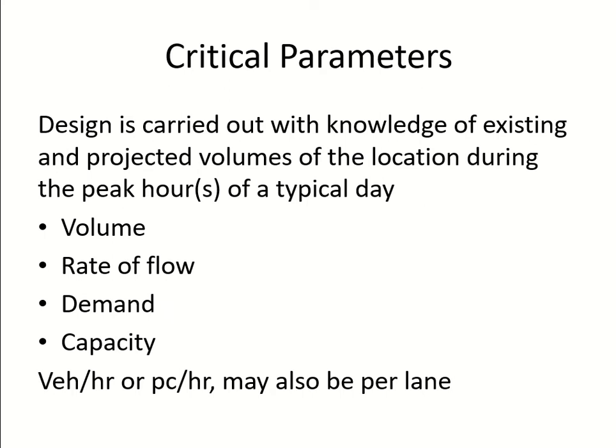There are certain parameters related to volume which are important for traffic engineering analysis and design. When you are designing any transportation facility, you want the existing volume on the facility, the existing demand, and the projected volume for the future. If the facility is supposed to last for 20 years, what will the demand be after 20 years? You also need to know the peak hours in the day, at what times they exist, and how long the peak period is. In certain cases it can be more than 1 hour, which is why you see the term peak hours.